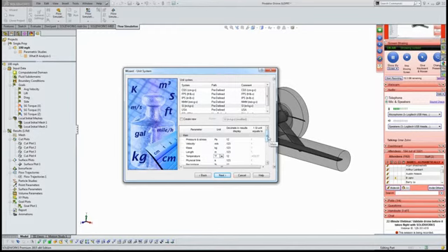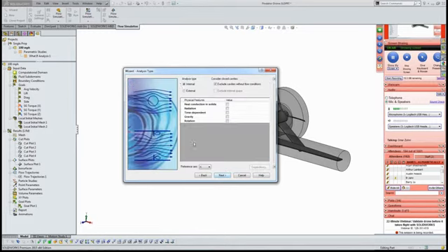So I'm going to use the SI unit system, but I'm going to make a couple of changes. I want to work in temperature in Fahrenheit and velocity in miles per hour. Sorry about that. I also want my angles to be in degrees. Let's leave it like that for now. So that's all I'm going to specify. You can always create your own unit system. You can see I have one down here called OZCFM. That's one customized for cubic feet per minute for a lot of internal problems.